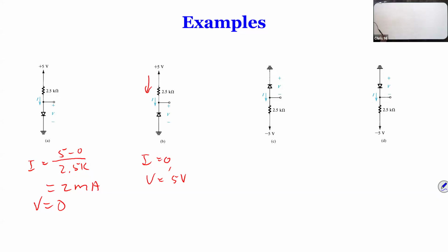okay, this one a little bit tricky because we got everything flipped, right? So you got minus 5 volts here, and you got a ground up there. So if you're not sure, you can start to do the assumption. Okay, assume this diode is like not conducting, off. What happens? If you assume it's off, the voltage across the diode would be -5 volts. Assume off, and then which means the voltage across here.